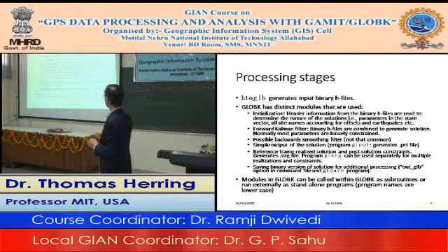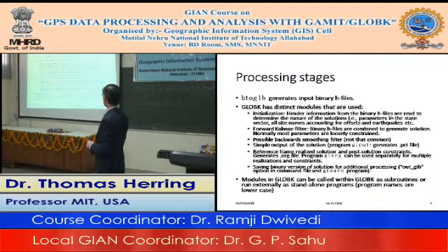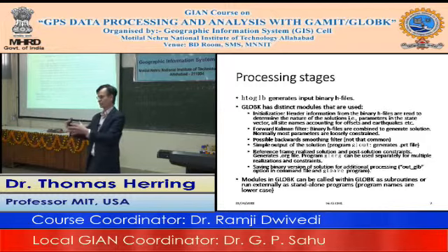And then finally, you may want to save your solution in a file which then can be used later in another GLOBK run. You do that with a command called out global, or it can be done with the program called glsave. And so this is what you do when you're, say, combining the 10 networks together to form the 500 station network.